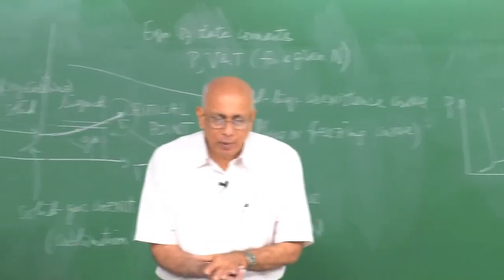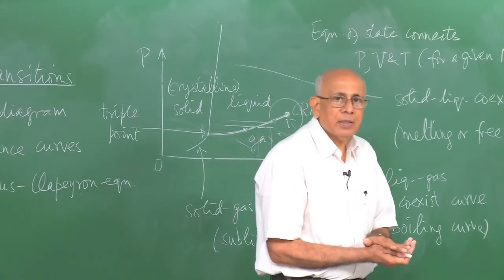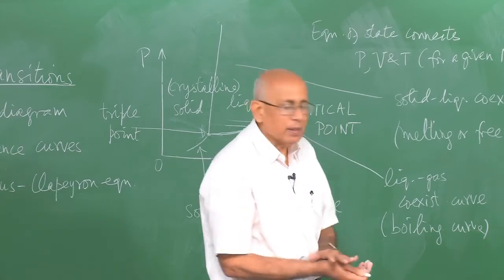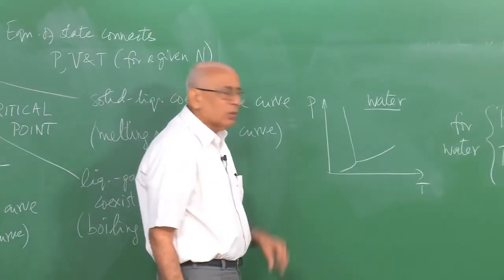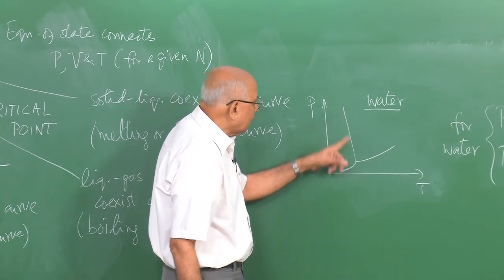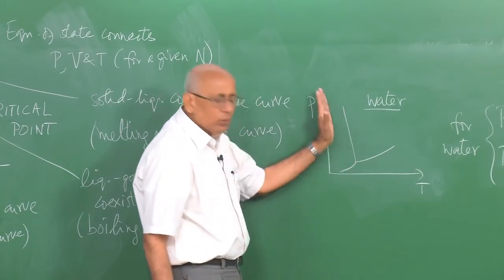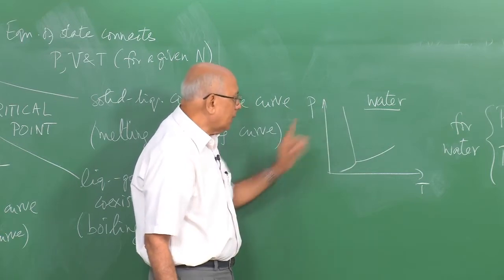The skate applies a pressure and the temperature is at 0 Celsius, it becomes a liquid phase at that stage and the skate slides. You need to lower the temperature further in order to solidify it. So that is what is reflected by the negative slope here, but the magnitude of the slope is still very high, but it is negative out here.